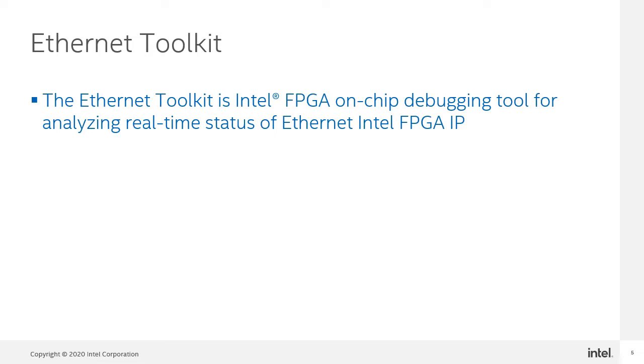Is your transmission medium broken or extremely noisy? How much work is your FEC block doing to correct for errors? The answer to any one of these questions could determine the reason for the link not working. And trying to figure this out without visibility into the IP core can be very challenging or become very expensive.